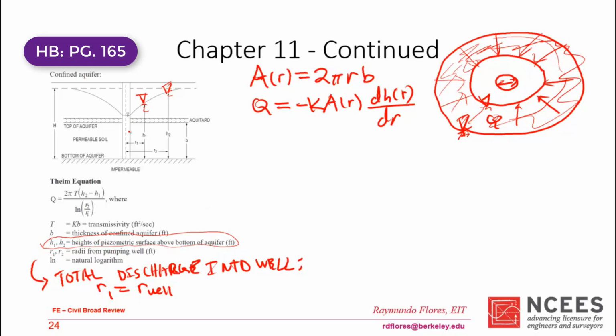And by the way, this is kind of funny because as this increases, as you get more and more water into your well, into your steel pipe, what's going to happen is your Q is going to be decreasing and decreasing and decreasing, and when it gets up to here, because H1 would have to be H of the well. So if suppose this were all the way up here, then you would have Q is equal to 0, right?